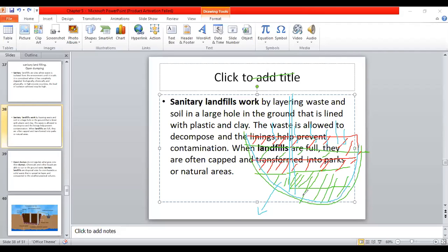And after some time, what happened? The decomposition was performed for this material wherever there is solid waste. And due to decomposition, what happened? During decomposition, not only is leachate produced, but also gases are produced. Which gases are produced? CH4, methane, carbon dioxide, H2S, and then some quantity of leachate. So these are going to be formed during this.